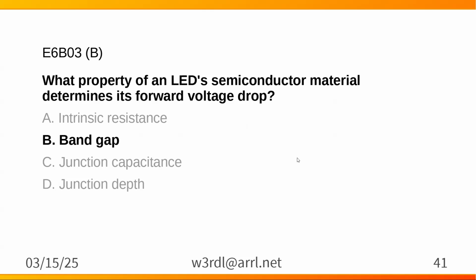And typically you're going to see bias voltages or barrier voltages in the volts when you look at an LED. Much higher. And they're all going to be different. Colors are going to be different because of that. That's how you get to different wavelengths. Plus special coatings that sort of phosphoresce or something and help change the colors a little bit.